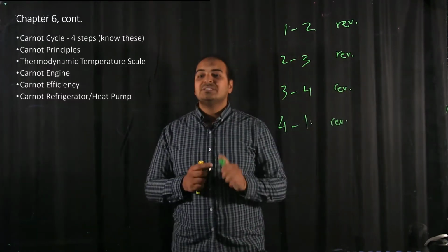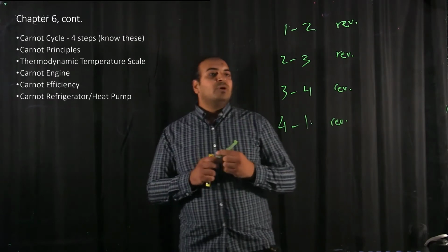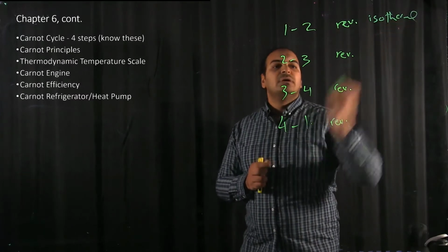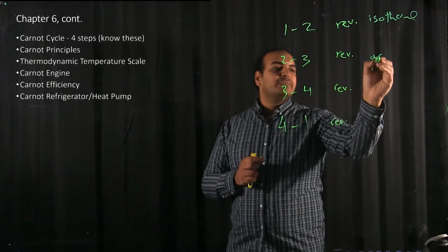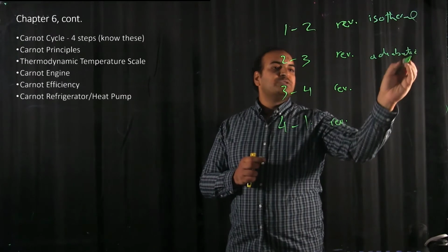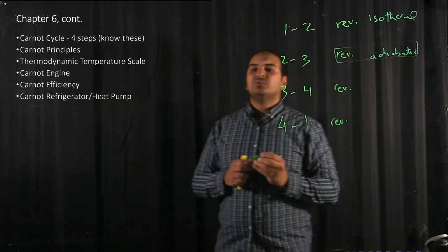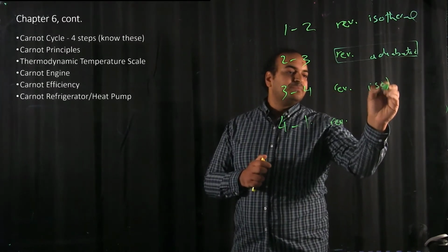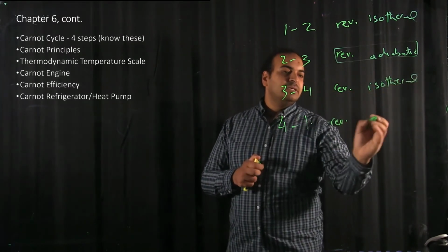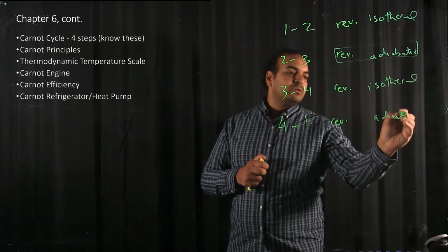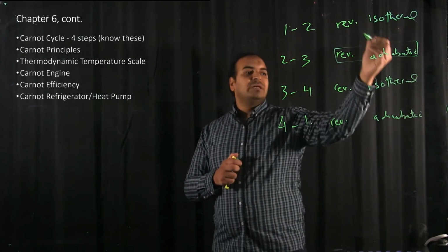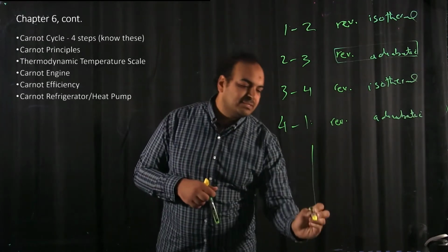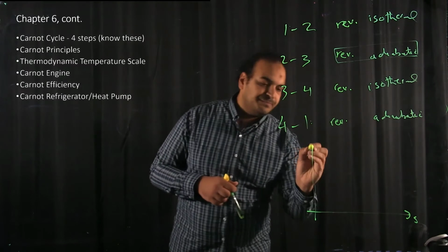It's called Carnot cycle. 1 to 2 is isothermal, temperature is constant. 2 to 3, adiabatic. We used to say adiabatic and reversible together is isentropic, 0 change in entropy. Then 3 to 4 is isothermal, and finally 4 to 1 is adiabatic. So again: isothermal, adiabatic, isothermal, adiabatic. Let's plot them in the TS diagram, the best diagram ever for this.